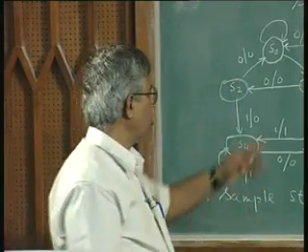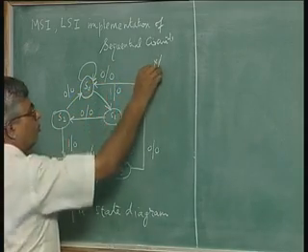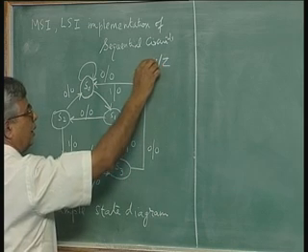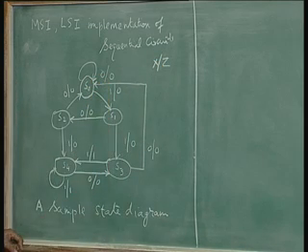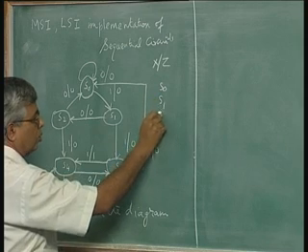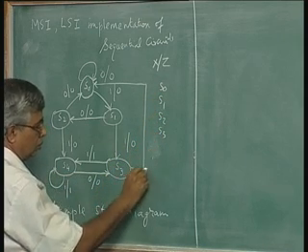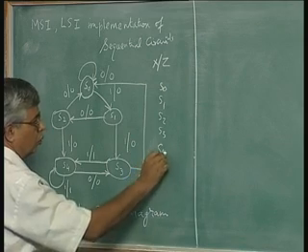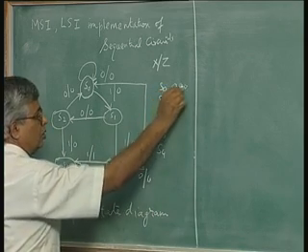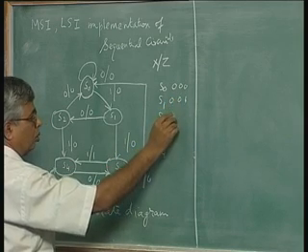We are assuming there is an input and an output, so we will call the input X and the output Z. There are 5 states, so we will call the states S0, S1, S2, S3, S4, assigned arbitrarily as 000 through 100. We are not using any assignment rules.